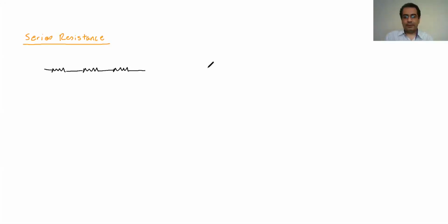So if I have a resistance like that, and then it goes there, and then a resistance like that, and there's a wire here, this is not series, because although the ends of them are connected together, there is a third element in between them. There's a third wire in between them. It should be only a single wire, nothing else between them. Then you can say that these are in series. If there's anything between them, even a single wire, then they are not in series.